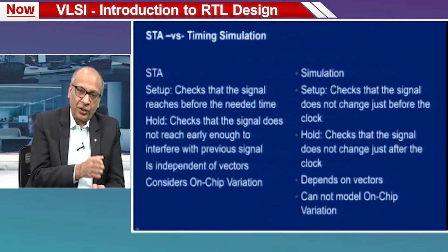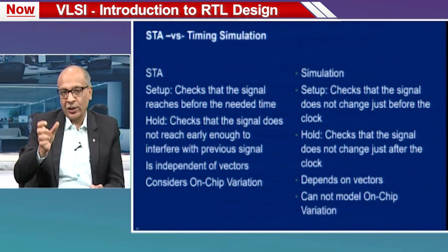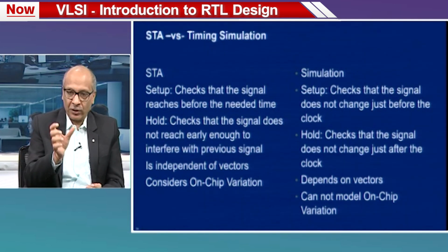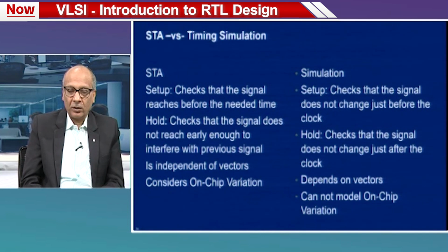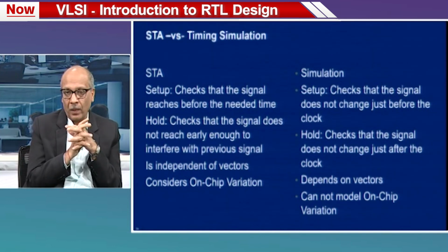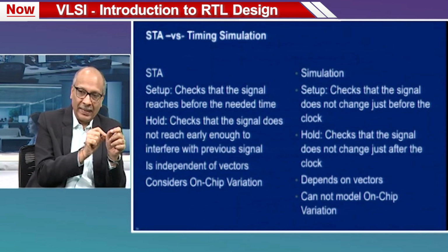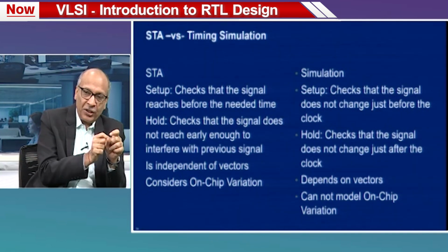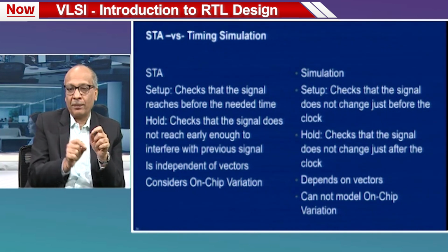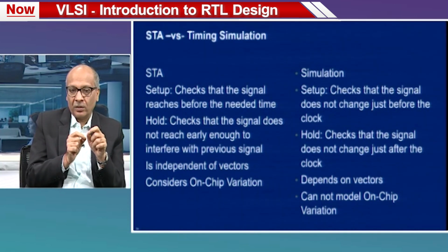Hold definition is after the clock edge, the signal should not change for a certain duration, for the duration of the hold. In STA, the definition is slightly different. In STA, setup means the signal should have reached before the setup time of the clock edge.